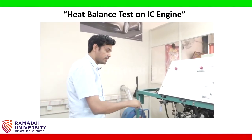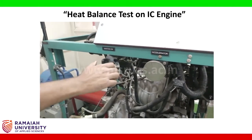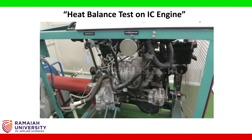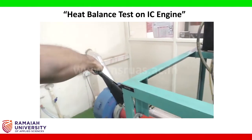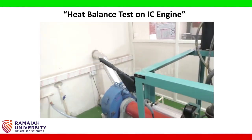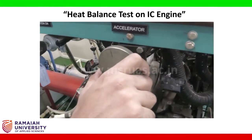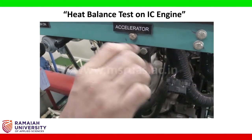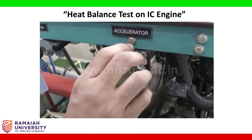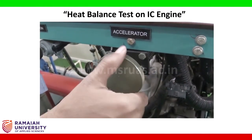Now to conduct the experiments, first, switch on the ignition key. Then connect the dynamometer to the engine using the clutch. Then give the acceleration through the accelerator here by giving 3 rotations: 1, 2 and then 3.